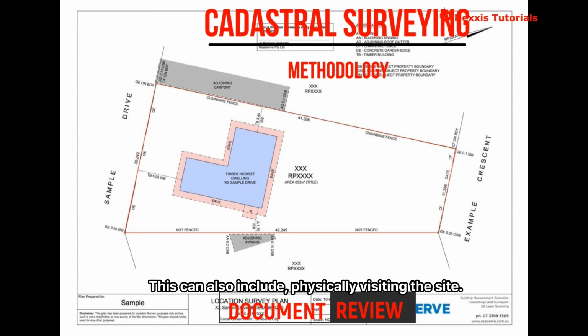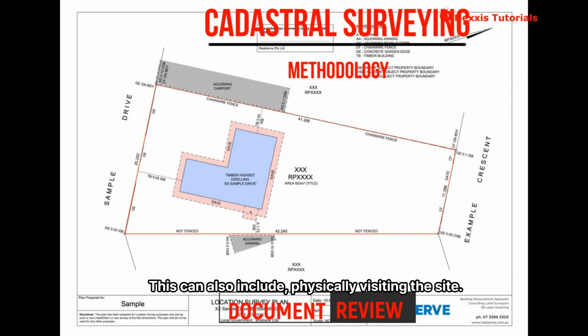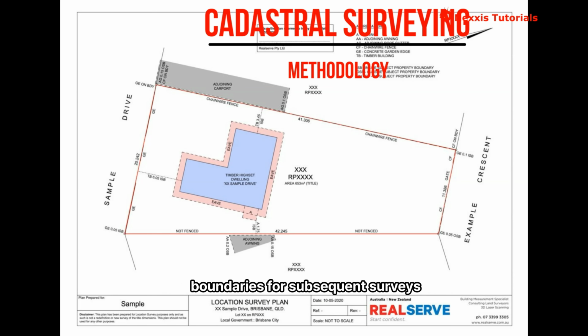This can also include physically visiting the site and assessing the boundaries for documentation. So what we normally do here is to go with the land owner or the property owner to the site and then physically demarcate or delineate the boundaries, or the owner can show us the boundaries for subsequent surveys.